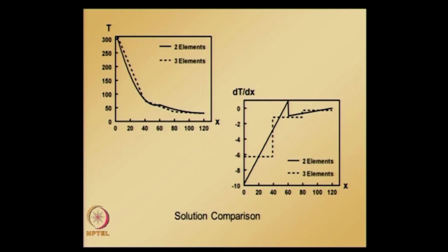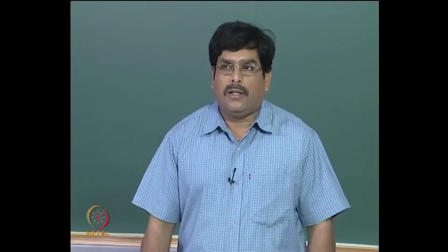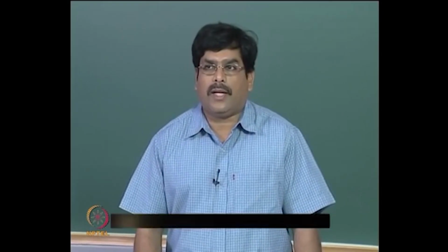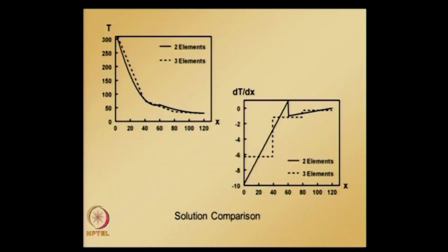So, that is expected, a large error in derivative of temperature, and so this demonstrates usage of higher order elements, and we have also seen while doing this example how to use numerical integration for evaluating some of the integrals required for assembling the element equations.